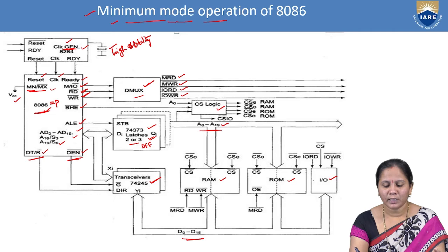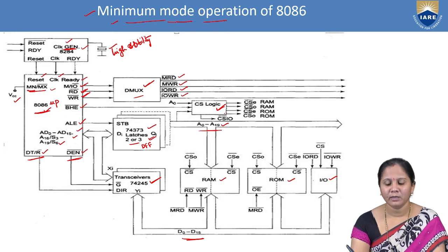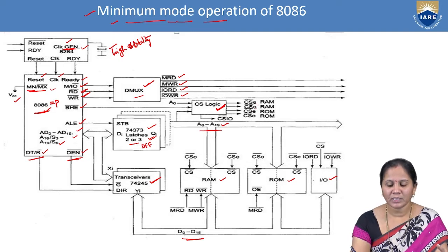Next, coming to the next important block, that is the chip selection logic. Generally it is used for selecting the address bank. We have an even address bank and an odd address bank. From which bank the memory should be selected will be decided by this chip selection logic. This is CSE, where the suffix E represents that it is related to the even address. The next one is CSO, where O represents the odd address. These signals will be used for memory mapping.